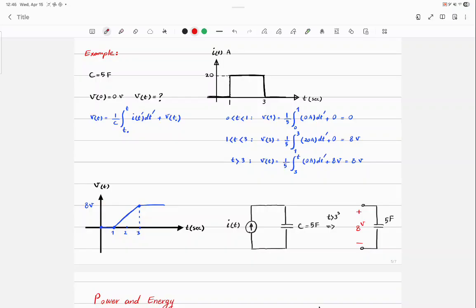Let me ask one more question. What's the difference between a charged capacitor and a voltage source? That's useful for the next lecture. A capacitor doesn't require any constant power. The voltage source doesn't need anything else. One is steady. The voltage source will give you 9 volts or 5 volts constantly. But this guy, as soon as it's connected to some other circuit, the voltage drop across it starts to fall off until it becomes completely discharged. Okay?